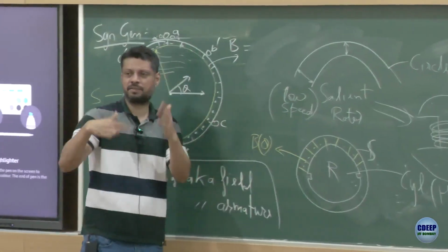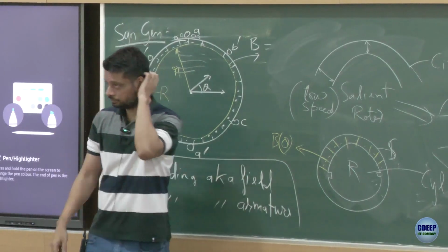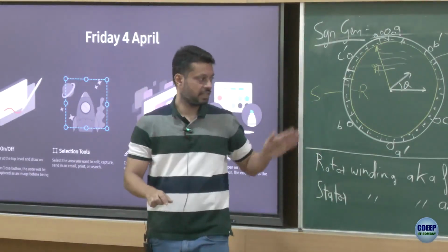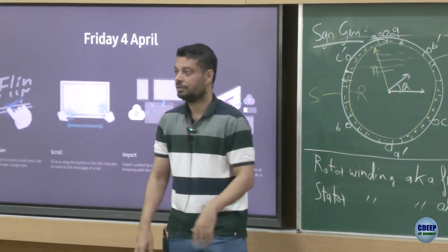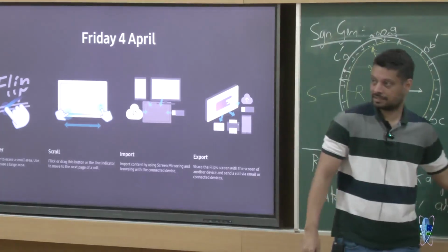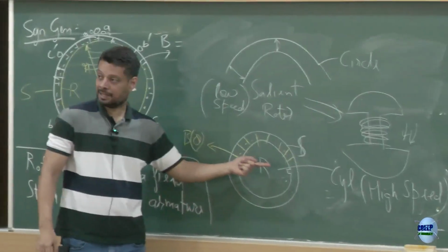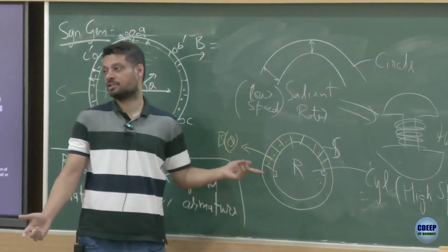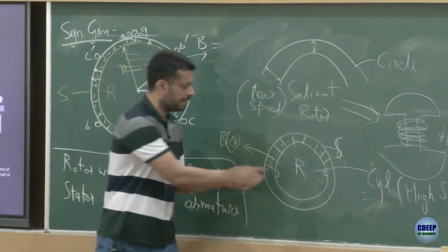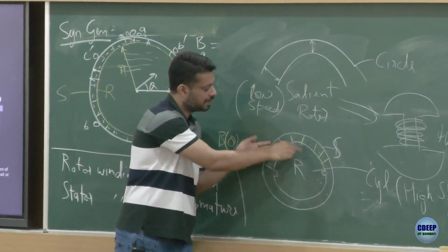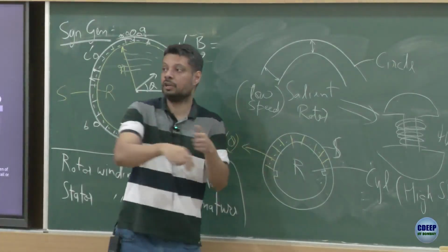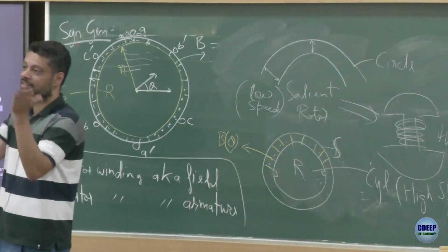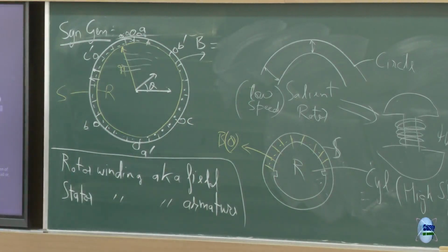No, turning is fine, we are not looking at turning. No, first of all it's stationary, nothing is turning. It's just stationary for now. We are only considering a stationary case. If we are exciting this coil, will we get a sinusoidal flux distribution? So here there is no reluctance, so flux can go anywhere in the rotor, no problem. Once it wants to cross, it would see all the crossings, all the resistances as equal. So it would just divide equally.